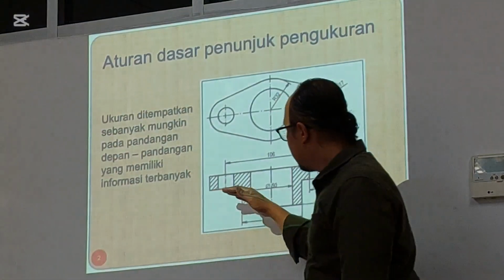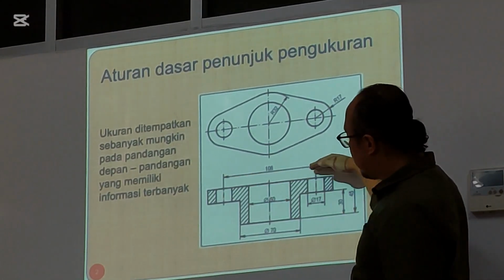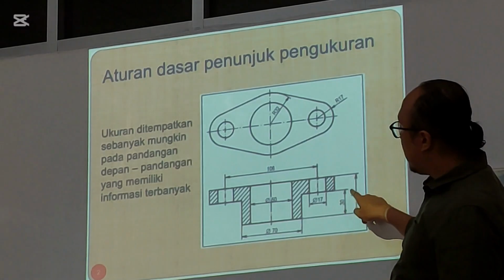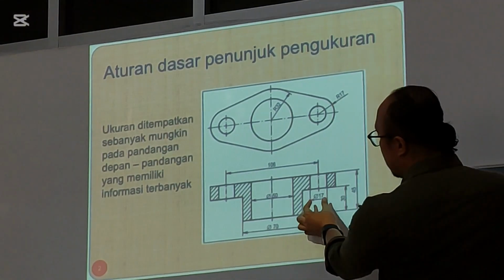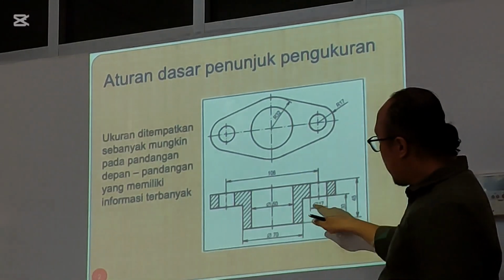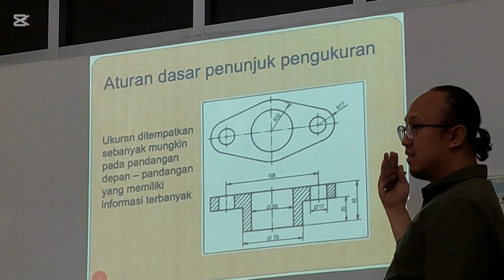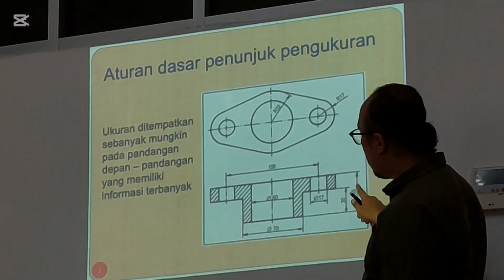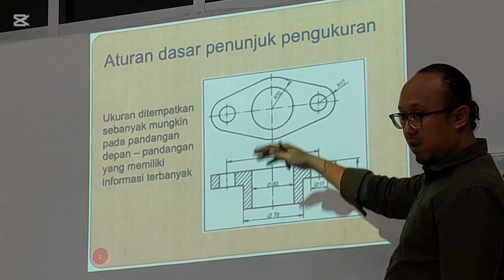And the position, if you put the dimension at the middle of the dimension line, for all of them, you also put at the middle. If there is not enough space, for example, if the space is too small, so you cannot add some dimension inside this, you cannot put in this area. You put at the right side area or maybe left side area, which has enough space. But if you found enough space, if you choose the middle, please use only the middle for all.